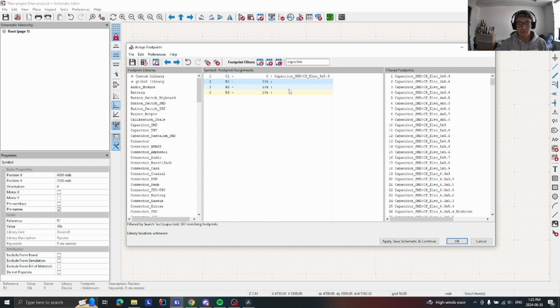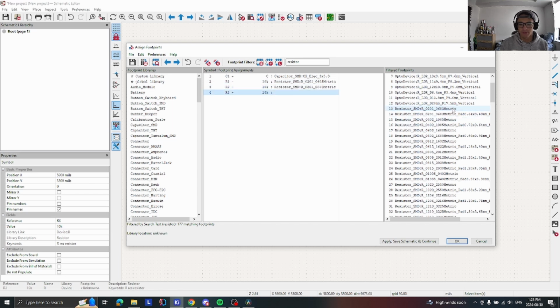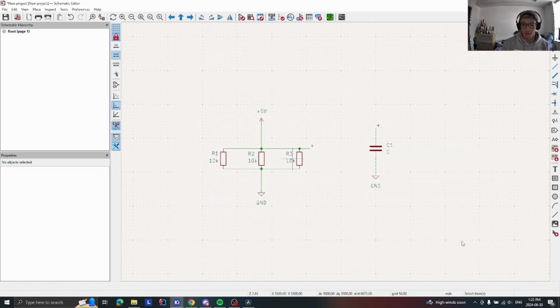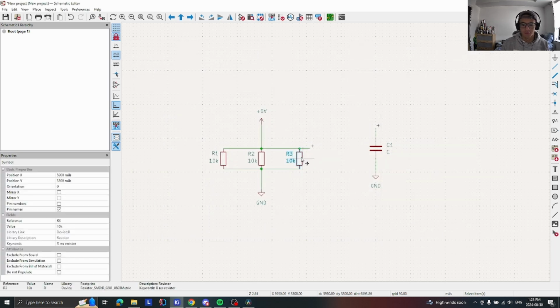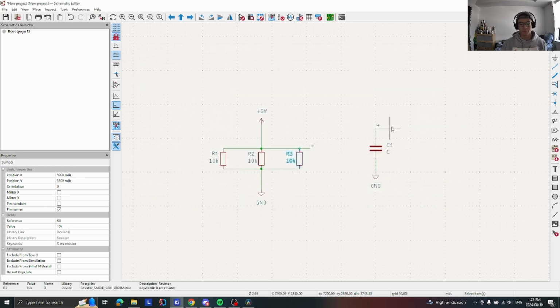And that's useful because let's say we have 3 resistors that all require the same one. In the other method, instead of having to double click on all of them, you can go ahead, click resistor, SMD, whatever, double click, and double click, and click OK. And you're going to see that it gets applied to all of them.